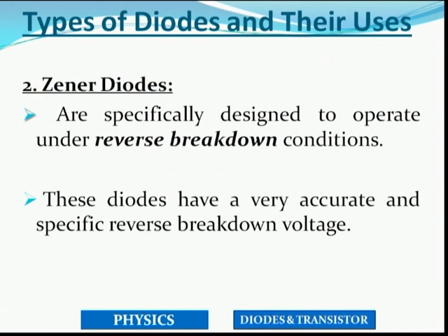Some of the diodes which we can discuss are related to the P-type material and the N-type material. The second important diode which is mainly used in electronic appliances is the Zener diode. The Zener diode is normally used in reverse breakdown, or in the reverse direction. An interesting characteristic of the Zener diode is that it can be used in forward bias like a traditional diode or the PN junction diode, but it is mainly used in the reverse bias direction.